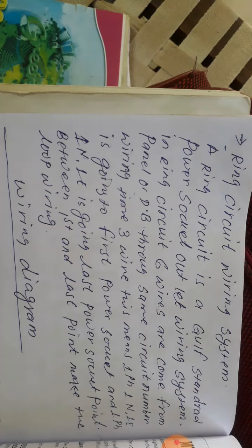and 6 mm wire is used for water heaters, and for AC above 1.5 ton we use 6 mm square. If it is below 1.5 ton, we can use 4 mm also. This is the Gulf standard wiring system. In the Gulf, 2.5 is used for the lighting wiring system, 4 mm for power sockets, and 6 mm for hand dryers, big AC, split AC, and some water heaters, okay. And 1.5 mm square is not used in the Gulf, okay.